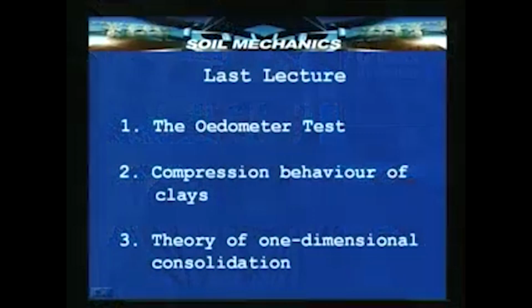Then we started discussing the theory of one dimensional consolidation. First of all, we said that one dimensional consolidation is an assumption, valid under certain specific circumstances. The major circumstances under which this is valid are: one, a very large loaded area, and two, a deep seated clay layer.